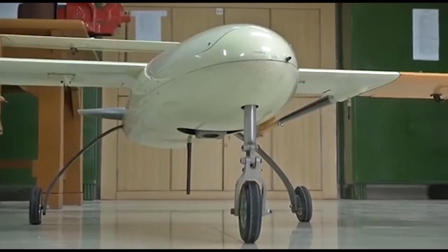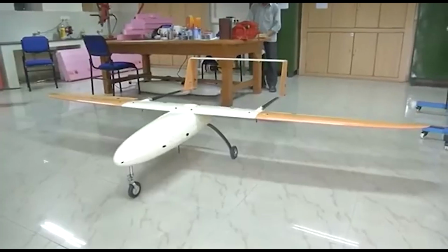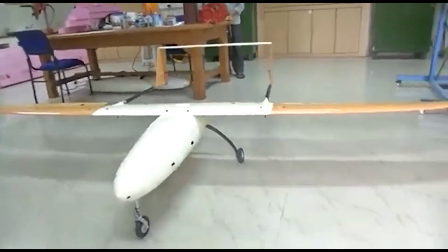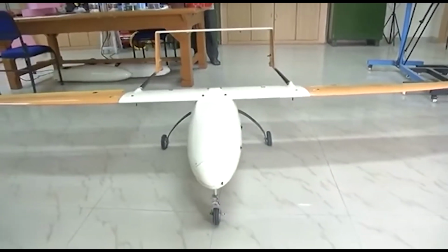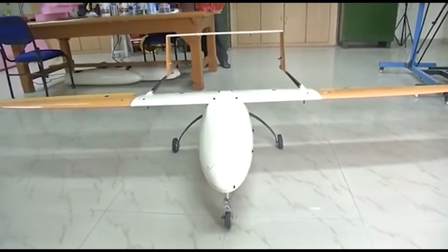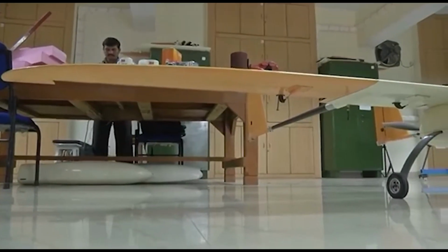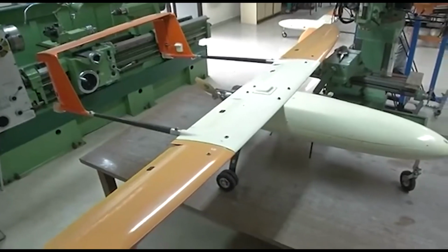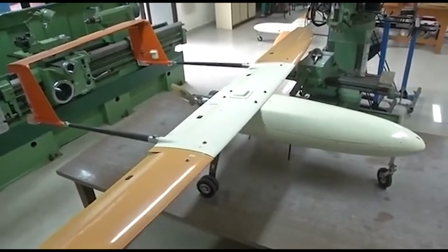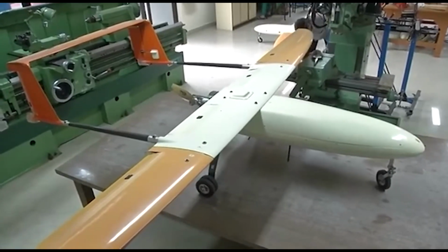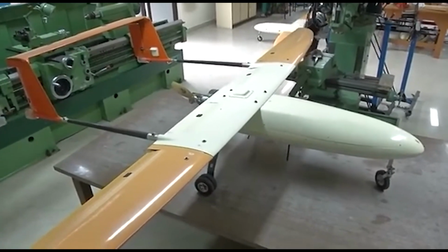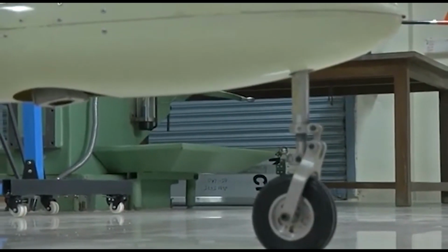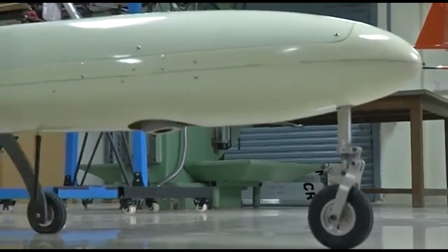And now this is our state-of-the-art low altitude, high endurance unmanned aerial vehicle which is fully autonomous. This is fabricated with glass fiber, carbon fiber and other sandwich materials. It has a wingspan of 3.3 meters. For the tail, we have three options. The one you are seeing here is the inverted C tail. The maximum takeoff weight is 25 kilograms. It can carry a payload up to 5 kilograms, which can be increased by decreasing the fuel weight. Currently, as a payload, a high resolution camera is mounted which can be operated from the ground station.